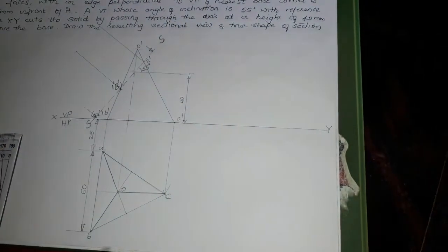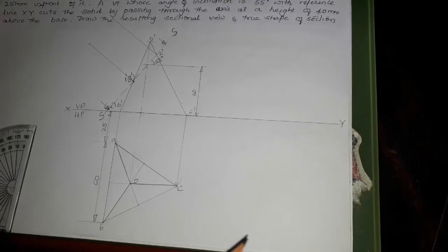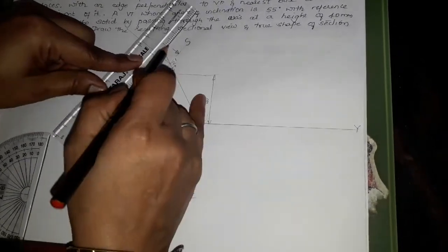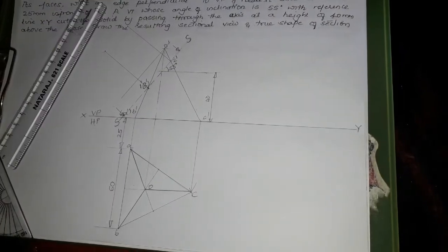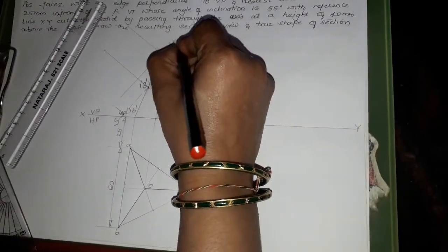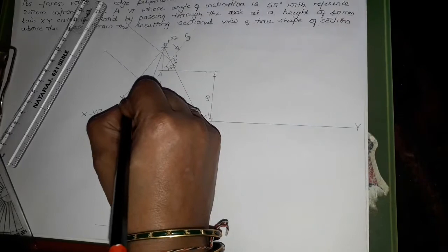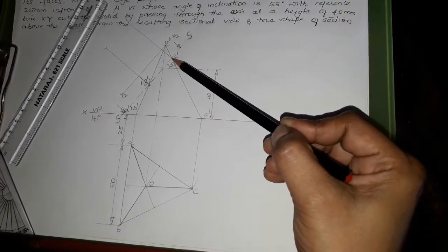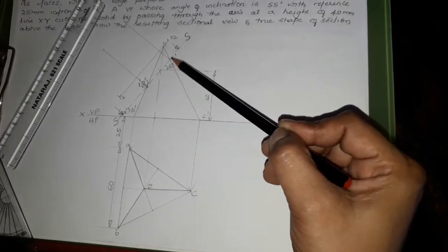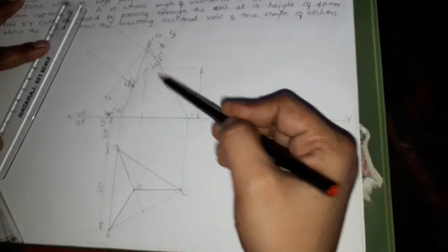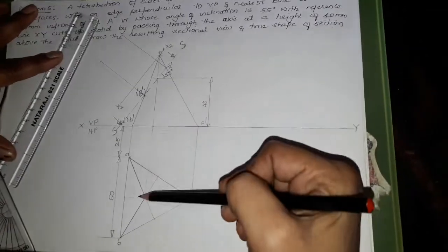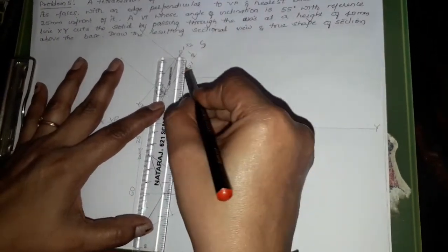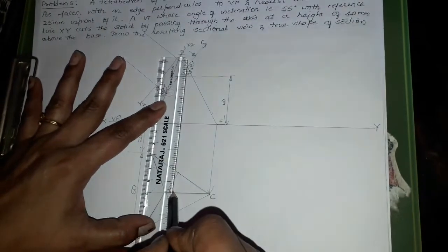Right. Now we should obtain the line x2 y2. The x2 y2 line is always parallel to the sectional plane. So just draw a line and name it as x2 and y2. As usual, you try to measure the distances where these points 2 and 1 are measuring. So trace back these points again to your top view. See here, draw vertical lines again from 2 dash,